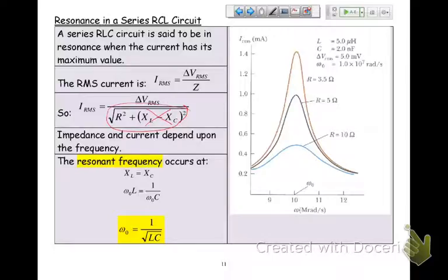And then my resistor is R. And so that's when you're at your resonant frequency, your impedance equals your resistance. Okay? It turns out that the smaller the resistor, the bigger the current, and so you get a sharper peak. So ideally, when I'm doing my LRC circuit, I want R to be kind of small. I'm going to maybe modify that in a minute, but kind of small.